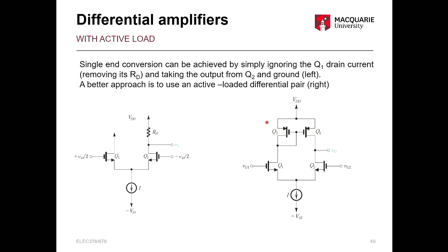You can step through what would happen to the currents here if you're interested to try to work it out, but we won't go through it in detail today. But essentially in the common mode, it will make no difference. It will just have the current flowing the same way, whereas in the differential mode, it will add the currents and you'll get double the current at the output, V out, okay?